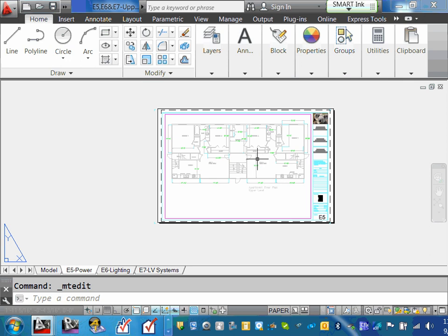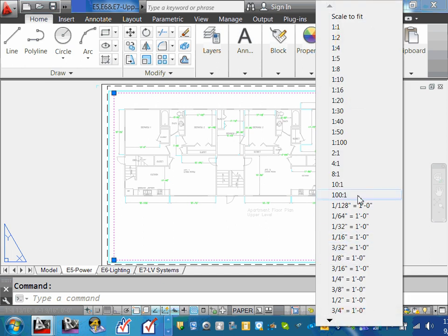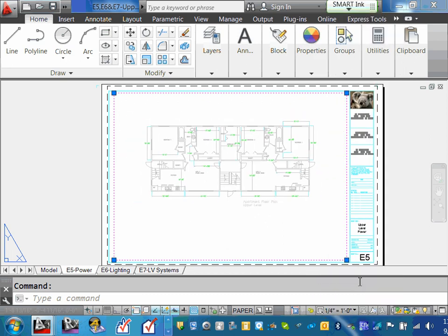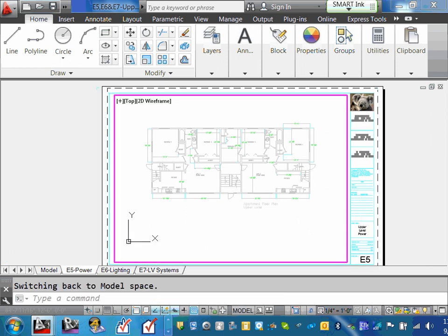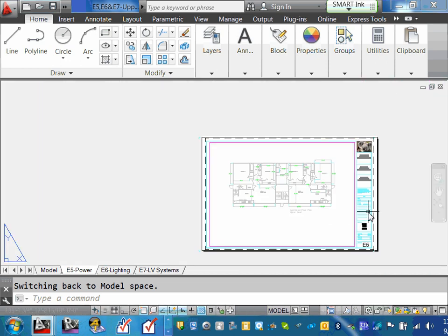Okay. All right. Now, here's what I would like you guys to do. I would like you to click on the viewport and make sure the viewport is sized 1/4. Go back to the 1/4. Did you guys scale it 1/4? Click on the viewport and right here at the bottom, pick 1/4. And right next to it, do you see the lock? Everybody can see the lock? Lock it. Now we can't mess with the scale. Now if you're playing around, getting in and out, it wouldn't mess up the scale.